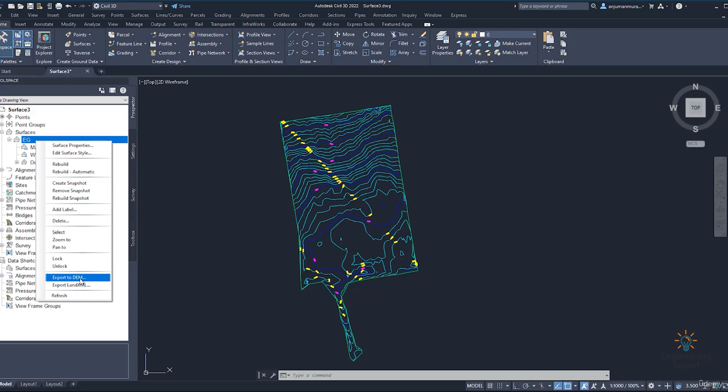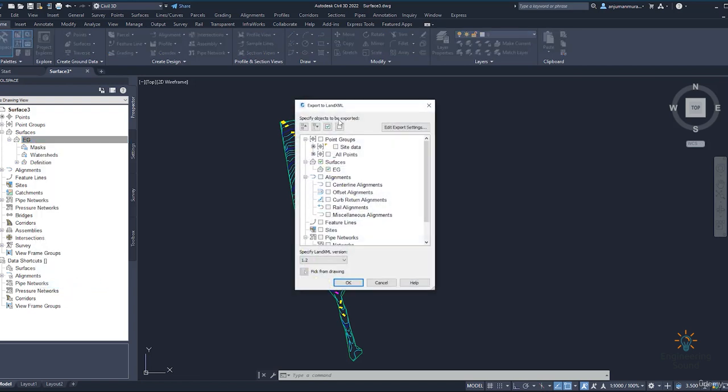So then you can use it in another software as a digital model, so the architect or any other engineer can work on this. So if you want to export as a land XML, you can easily export as a land XML. Mostly when we are working in Civil 3D, we export as a land XML, so it can easily be imported and attached to the file again. So click on this export XML. So this will give you this option. If there are any unnecessary options, you can just close it.